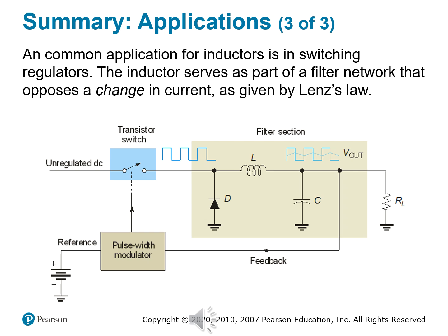Everything, right? According to Lenz's law, the inductor opposes rapid changes in current. So when the transistor toggles on and off, the inductor pushes back. It stores energy when current rises, it releases energy when current falls, and it acts as a current buffer between the noisy switching input and the smooth load output. This is important because without the inductor, the voltage would spike and drop with every pulse. The load would see erratic, unusable power, and the circuit would be less efficient and more prone to noise.